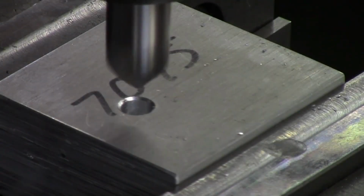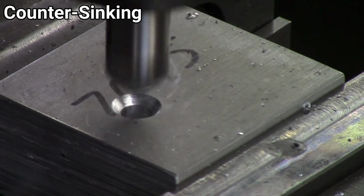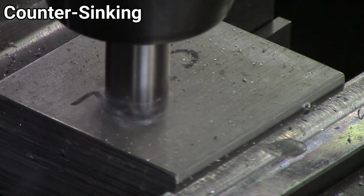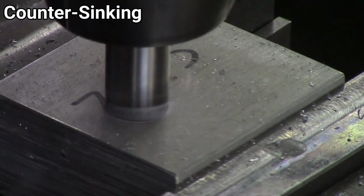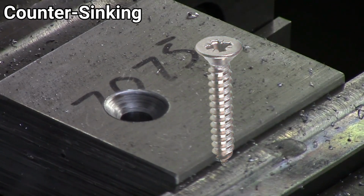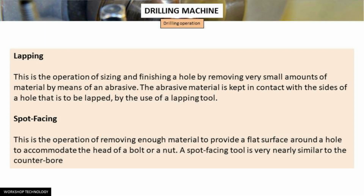Next is counter sinking. A counter sinking operation is shown here. This is the operation of making a cone-shaped enlargement of the end of a hole, as for the recess for a flat head screw. This is done for providing a seat for the countersunk head of the screw so that the latter may be flush with the main surface of the work.